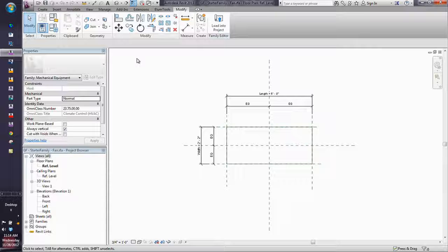When we're trying to calculate true pipe lengths, I have a value called CEL, which is connector engagement length. I've set that up as a dimensional parameter, and I have it in a schedule. In my pipe length schedule, it only applies to hub-type pipes, and anything that has a female end assigned to it, we add that CEL value to it. Then we get a value called true pipe length. I've got a shared parameter and a formula that takes the actual length plus the CEL to create true pipe length, and that's what I use for my estimating. If you haven't done that, it's a really easy step. You do it as a calculated value. Let me set the schedule up for you real quick, and I'll show you how this works.